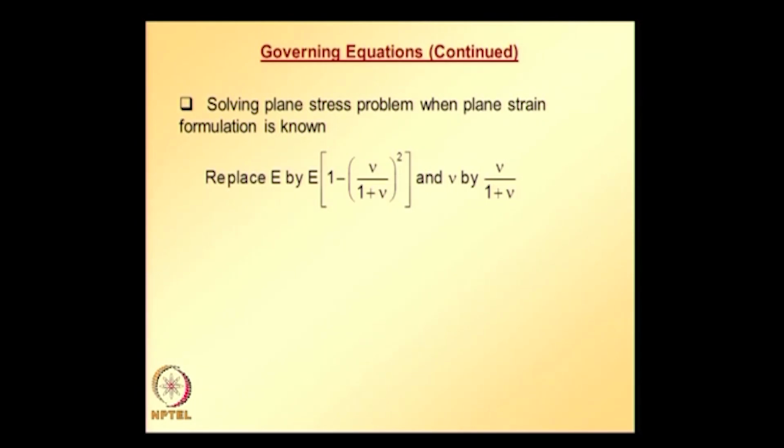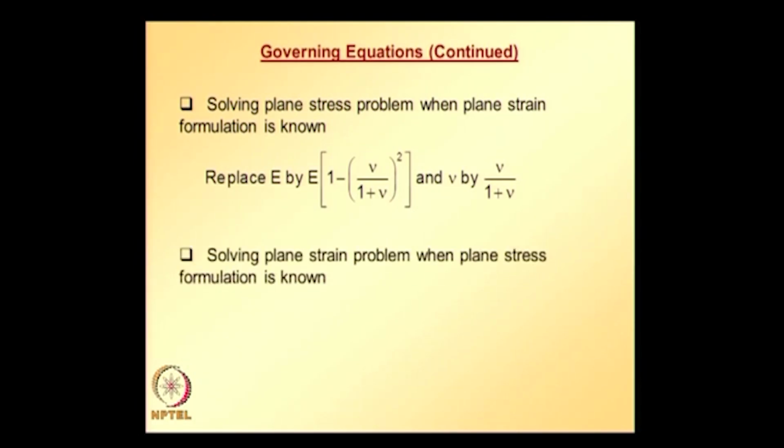So, if the plane strain formulation is known and you want to solve a plane stress case, do this substitution, and for solving a plane strain problem when the plane stress formulation is known, do the corresponding kind of substitution. So, with this understanding of equivalence, if we have any one of these formulations, we can easily solve a problem under a different assumption.